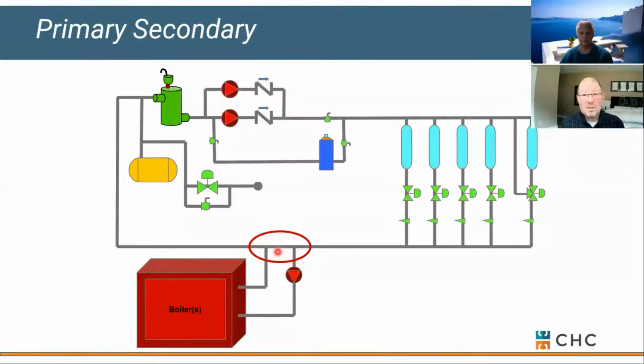And whatever you do, don't put a check valve in there or a balance valve. Okay, this piece of pipe is kind of sacred.